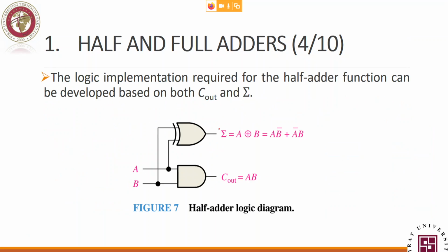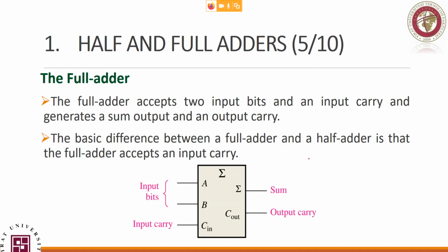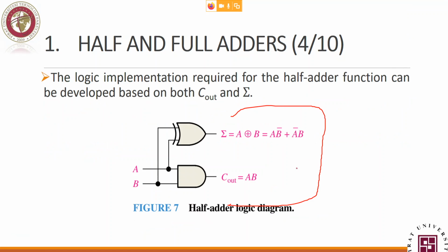So half adder, again, we have two outputs. These are the two outputs, and we have two inputs, one single bit for each. All right, so now for the summation we XOR these two bits, and for the C out we AND these two bits. All right. Now, for the half adder, we have a problem. I said I will explain about it in a while. The problem with the half adder is that we don't have a C in, the carry in.